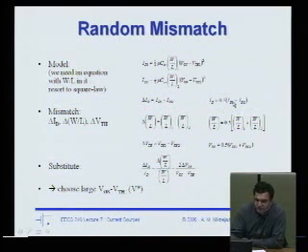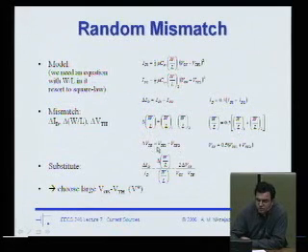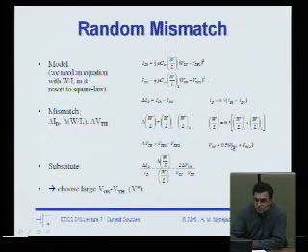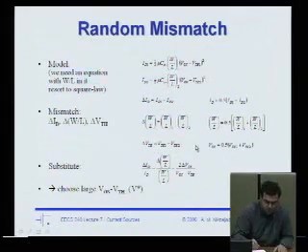So the way you do this is you define average quantities and difference quantities. The average current obviously is 1/2 ID1 plus ID2. The average W over L is just that. The difference in WLs is that. Again, you have a difference in threshold voltages and an average threshold voltage. If you substitute, you invert these equations, you write VT1 as VT plus delta VT, and VT2 as VT minus delta VT, for instance. You plug all these in, take the difference, you do some algebra, you get this nice clean expression. Okay, so let me write that expression a little bit larger here.